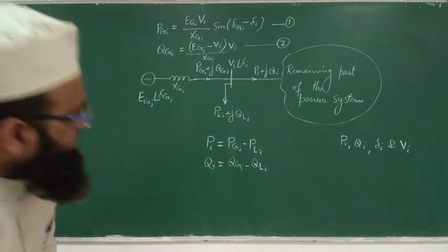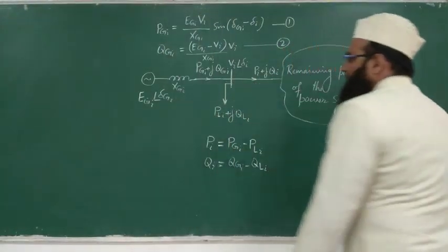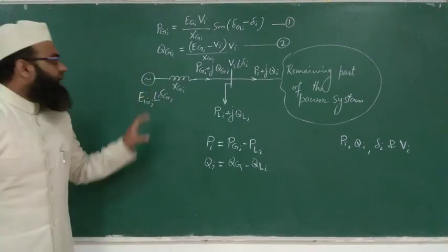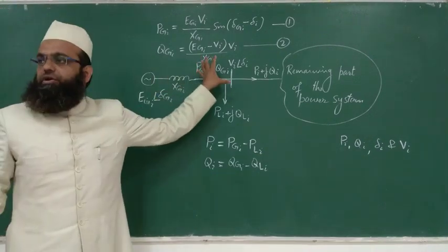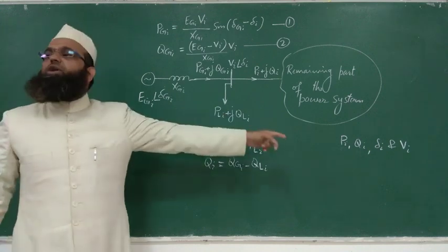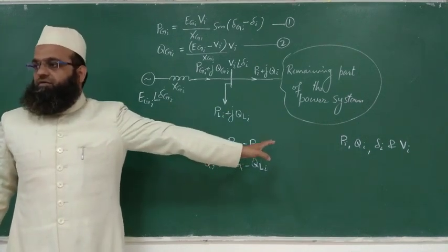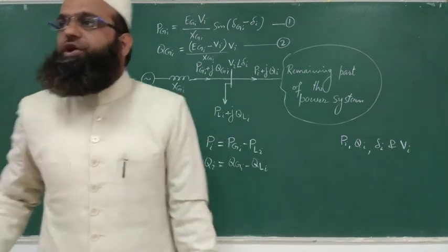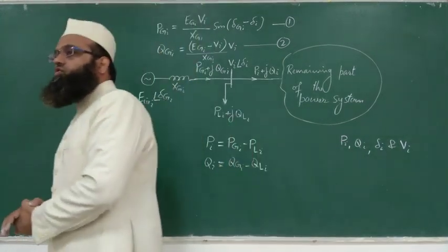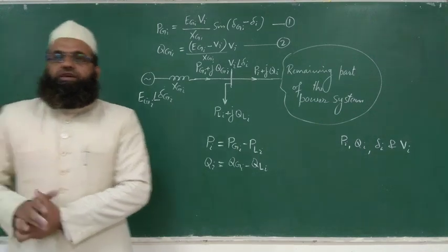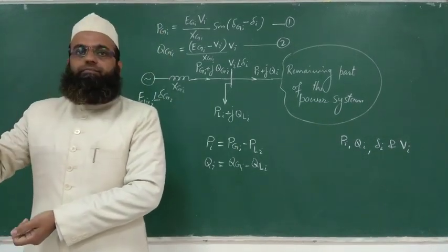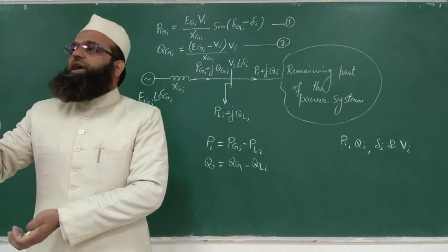Okay, one more thing. If you have changed its excitation and it has reached its maximum capacity, and still more Q demand is there, then what will you do? It can't supply more than its capacity. So in that case, you need to control voltages with the help of some other VAR sources.